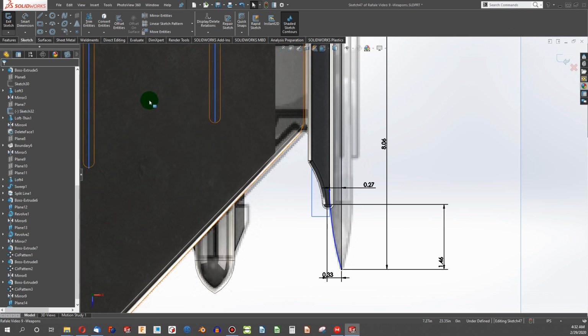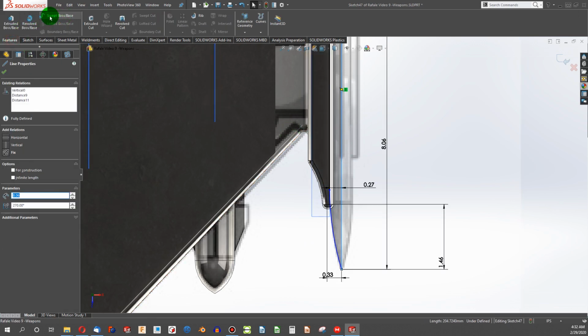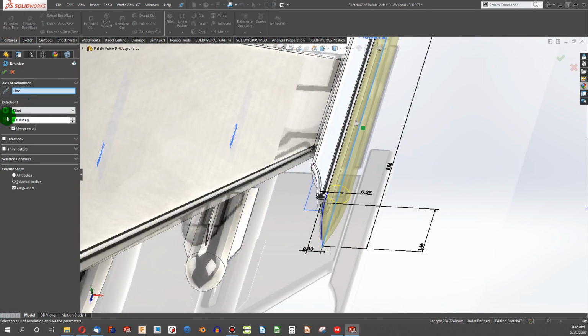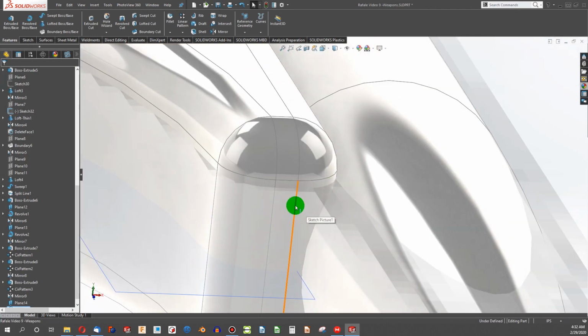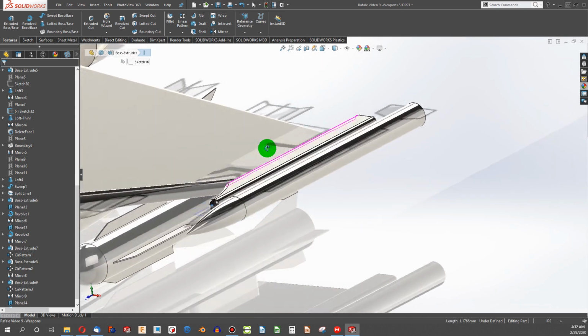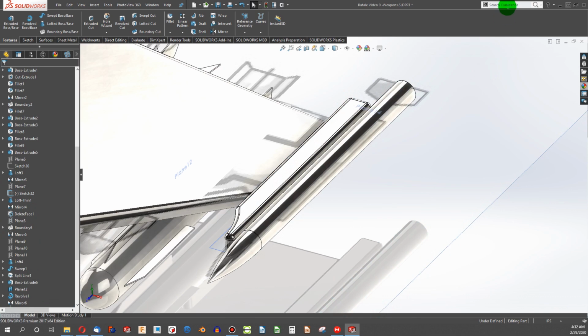Let's do a revolve. We'll highlight this line, features, revolve. And here's the key for multi-bodies, right? We're going to uncheck this merge result and shabam. You'll notice you have tangent lines right here and everything. There's no hard line there because these are two different bodies that are completely overlapping. When you have multi-bodies, you can do cool stuff like this, right? You can highlight both. Actually, I won't highlight both.